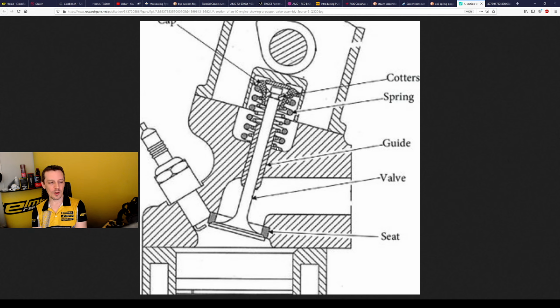You can do this partly with a beehive type spring, so you don't have a constant radius, and you can have all kinds of variable pitch that will also help, so that the whole spring doesn't have the same natural frequency. That's a way to get around natural frequency issues. Those issues typically arise when you start really maximizing accelerations and want to run at as high RPM, as high valve accelerations as possible.